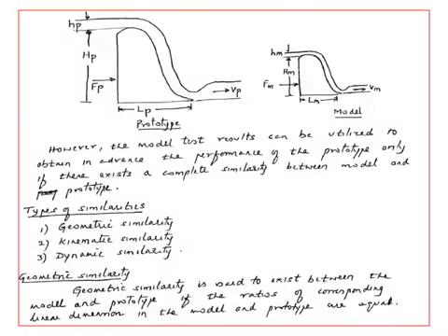So now this is the prototype of a spillway with its height as h suffix p. Head is a small hp, where the force exerted by the water is Fp. Similarly, the velocity in the tailwater may be like Vp. So the small scale replica of this is built, which is to some scale, and now this is known as the model, whereas this is known as the prototype.